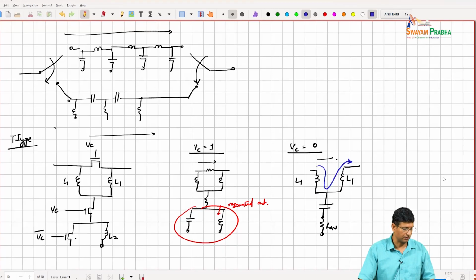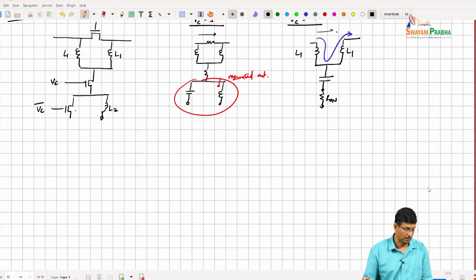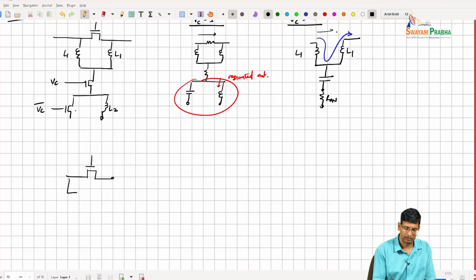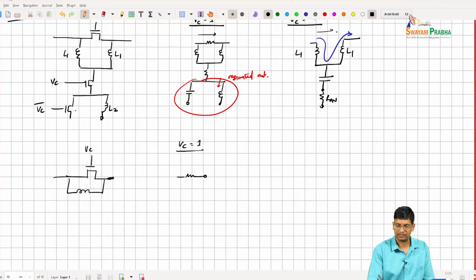But just to also highlight one thing in terms of implementation, right? So, for example, in the paper that I'm showing now, in order to implement the smallest phase shifter, in that case, it was a 5-degree phase shifter. They basically just have a switch, right, and an inductor, right? So when the switch is on, this is just a resistance, right?